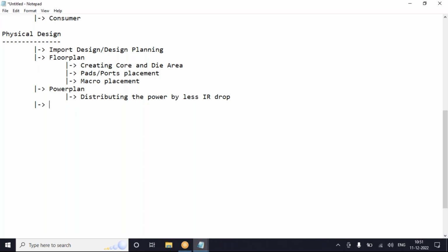So in this power plan, I'm making sure first that I made serial connections, or let's say parallel connections, without seeing what type of cell or what type of object I'm going to be using there. Made the connections and checked it. Okay, it's good. My power is coming and expected power is coming. Good. I'll move forward to the placement stage. I'll place the small cells now.